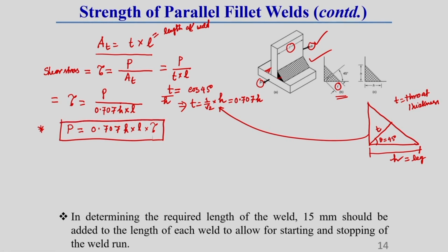Here there is only a single weld, but we know for a fillet weld to be in proper strength, generally both side fillet welding is required.